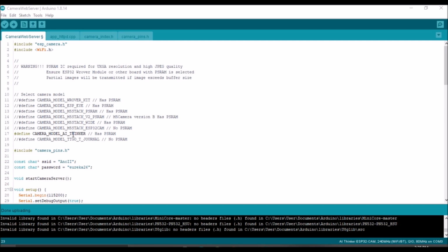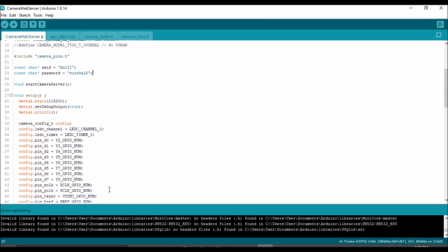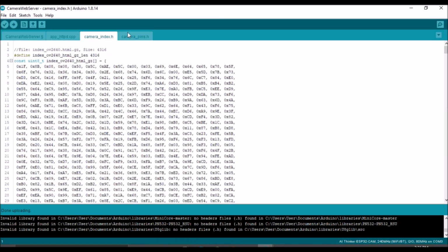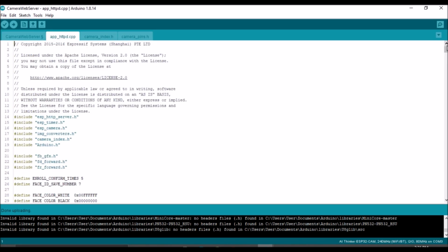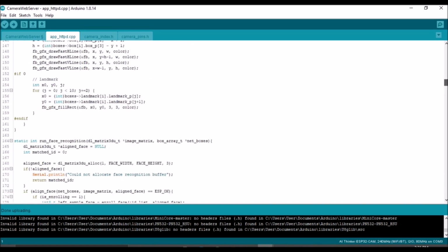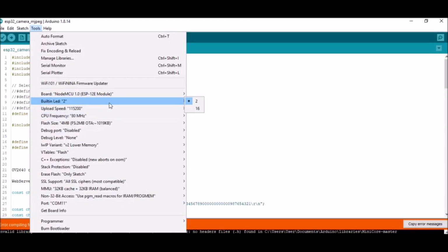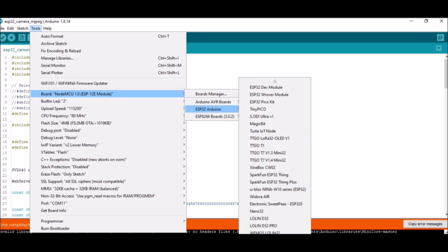The code contains where you can put the SSID of the Wi-Fi network, and also include the password of the same network. Once you include this, you can proceed to uploading the code onto your ESP32 CAM dev board. You can check the rest of the source codes to see which part of them needs editing or modification. Once you are through, you can proceed to uploading the code.